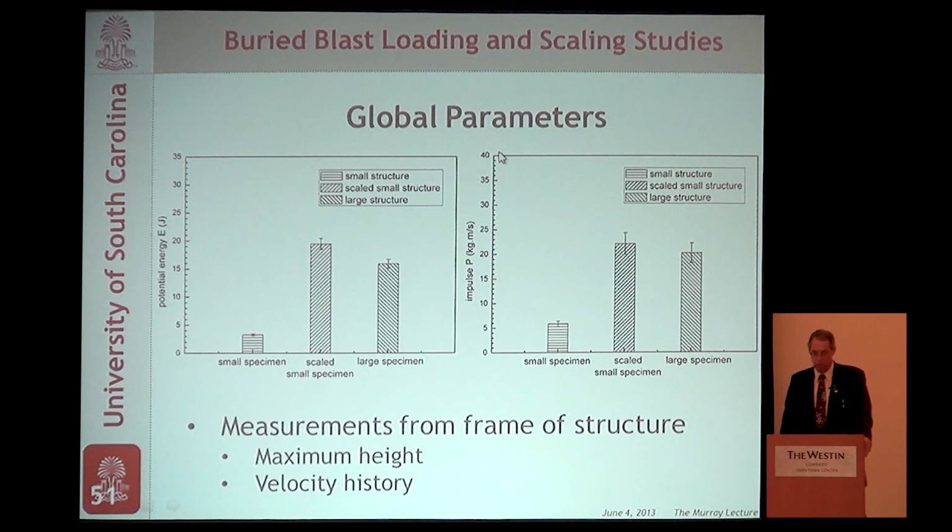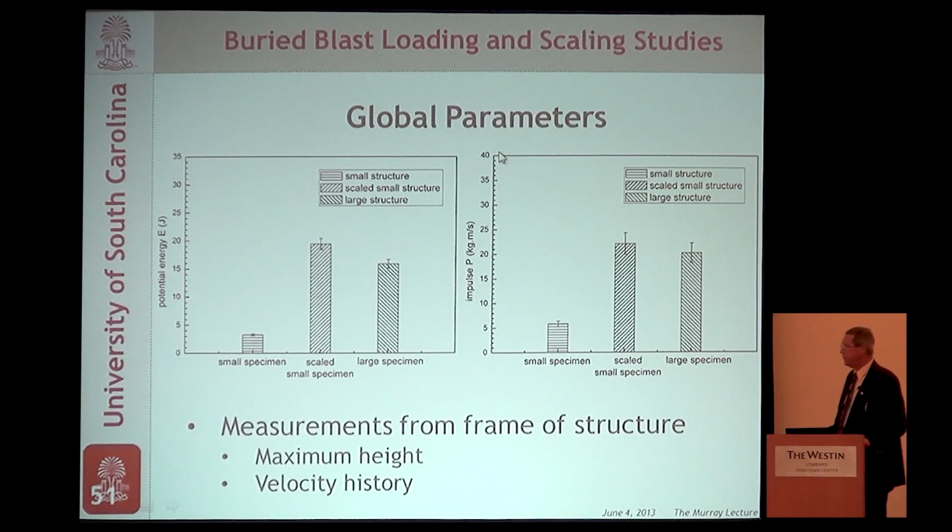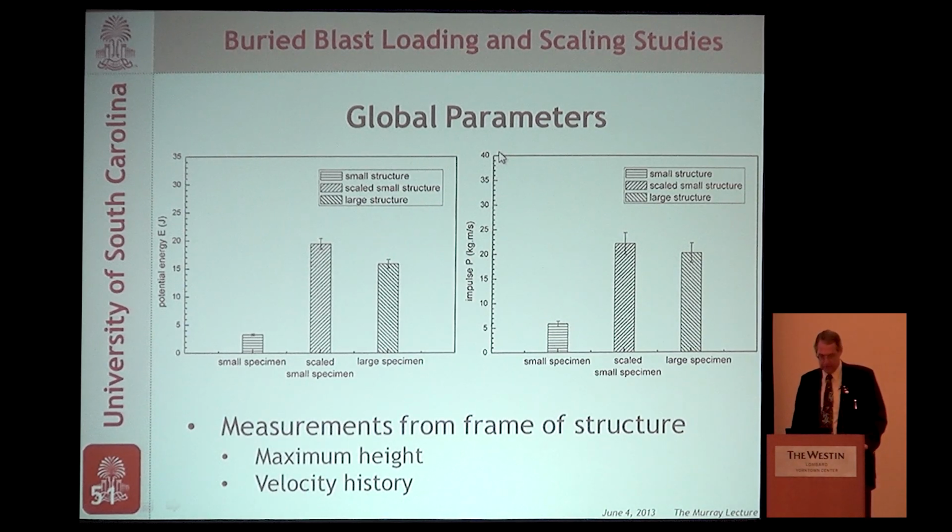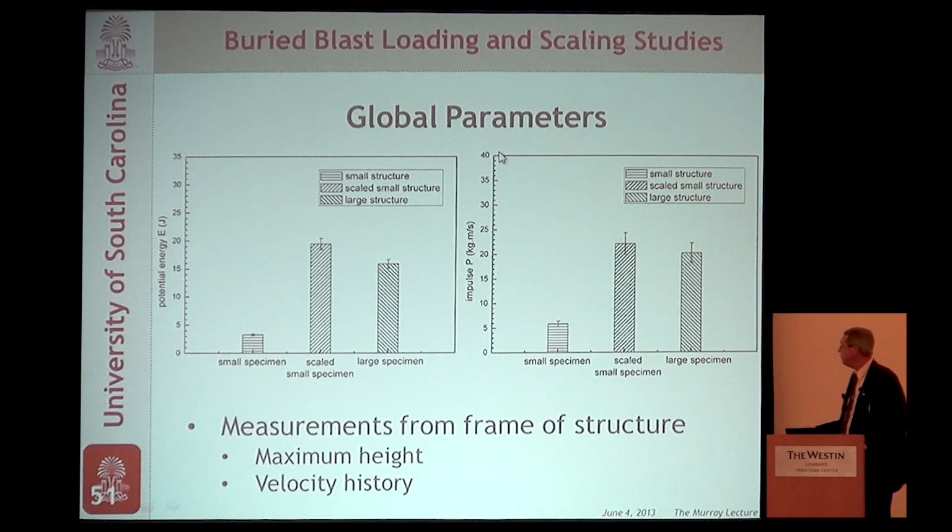Finally, we look at the global measurements. That is, how high did the specimen rise during the blast? In this, on the left is the height, that's the potential energy. And on the right was the impulse, the mass times the initial velocity. How did they compare? Small specimen, scaled small specimen, and large specimen. These should be the same.